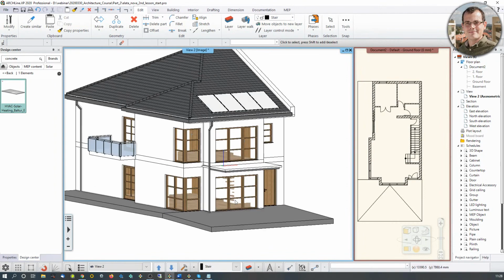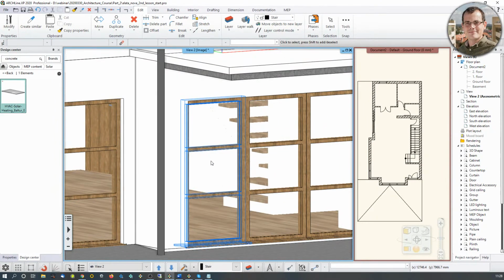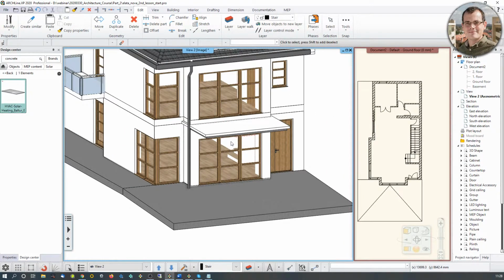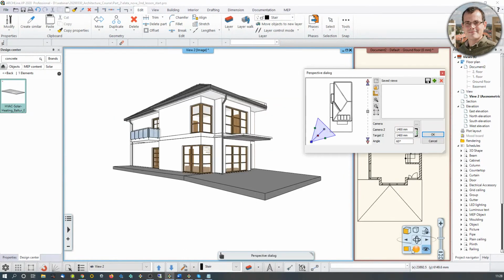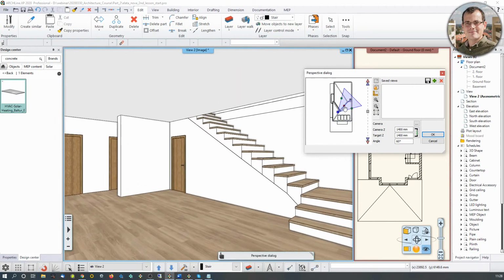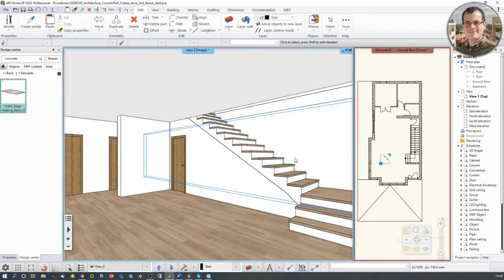I want to look in, but I can't do it because I'm still in axonometry. Remember, we covered yesterday, so if you want to jump into your model, you have to switch into a perspective view, which allows you to drag your viewport and go into the model. And I'm just going to add the view over here, making sure that I can jump back here.